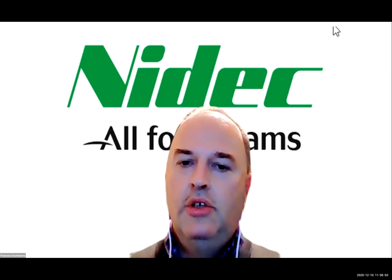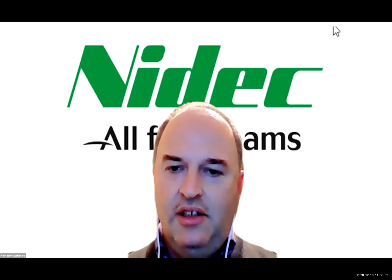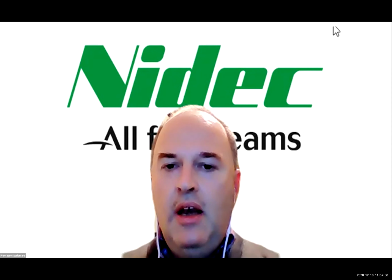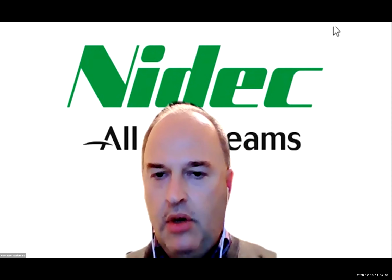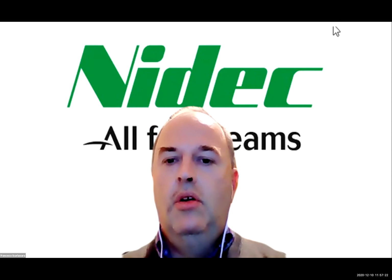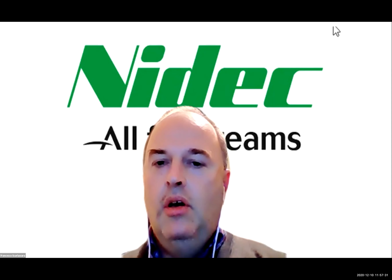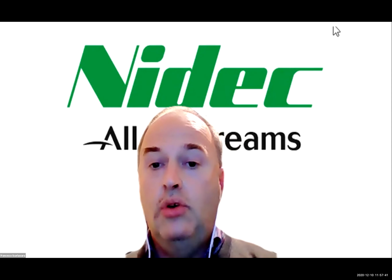Another question, Francesco, is it harder to achieve smaller interbillet time when we are dealing with short billets? Yes, it's possible. If you have a 12-meter billet or something like that, it's easier to have a lot of tonnage in production. But if the billets are shorter, it's still possible to run with a shorter interbillet. Depending on the length of the mill entry rollerway, you might have 2 or 3 billets waiting there to enter the mill, because the billet will get rolled very fast, and you cannot wait for the billet to be rolled in order to call the next billet from the furnace. The next billet from the furnace must already be there on the rollerway, close to the stand.